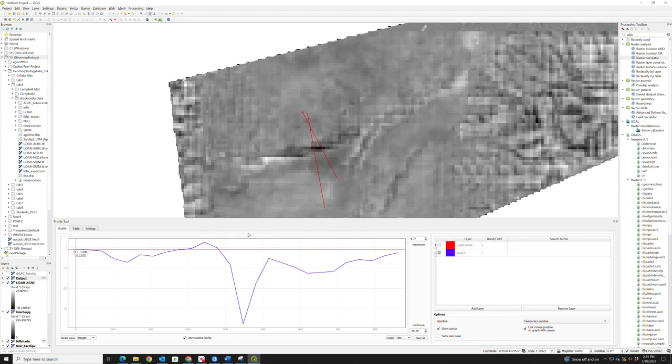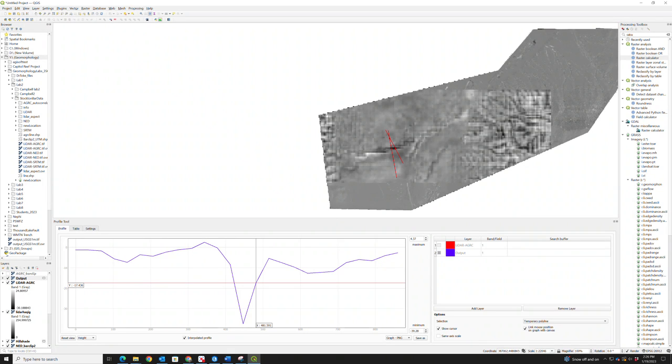So there's some areas that the SRTM, what was it? It was NED minus SRTM. So the SRTM is way higher than the NED. And remember, it was a radar image, so it could have reflected off something taller rather than representing the ground surface. So that makes sense. It could be negative. We should probably broadly be negative across the image in that sense. But yeah, so hopefully you see that QGIS is a really cool and useful tool, and hopefully this helps you get started with DEM analyses generally and profiles as well.